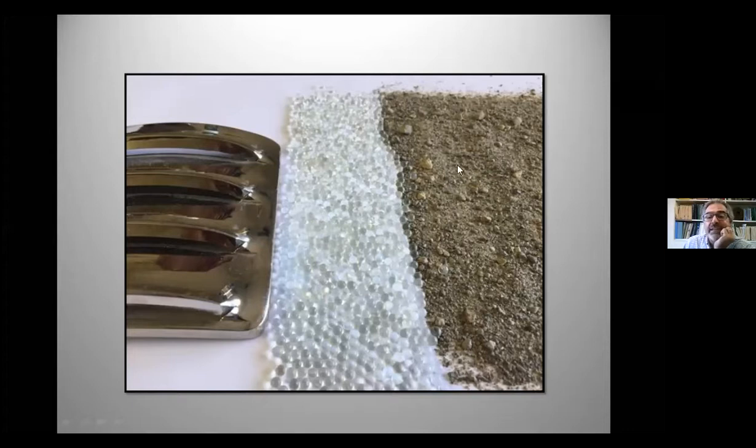An aquifer like this, or formation like this, where you have fine, medium, and some of these coarse grains, as I'm showing here by my cursor, if you have an aquifer whose texture includes these, then these will be very suitable to line up with the beads, because what I believe happens is you actually do some sorting. You winnow out the fines close to this interface between the beads and the aquifer, so you build up your filter zone right out here. You take out the fines, you leave a coarsening layer right at this interface, and now you have a nice clean transition from your aquifer to the slots. And that's some of the advantage of the beads.